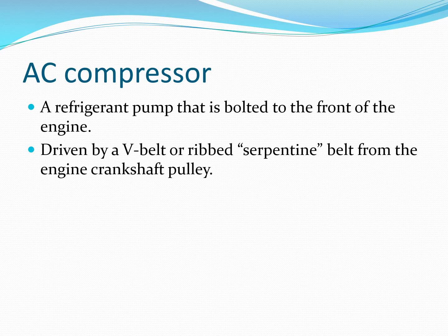As far as I know, every hybrid or electric car on the market right now does have air conditioning. But if you start thinking about how those vehicles operate, there's no internal combustion engine in an electric car. And the internal combustion engine on a hybrid car only runs part of the time. So that means we're going to have another means of running an air conditioner compressor in those vehicles. Those vehicles are going to have an electric air conditioner compressor. And quite often on an electric car, that is on the high voltage side. So just be aware of that.